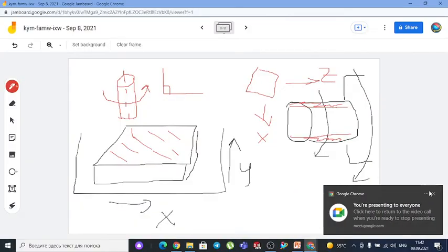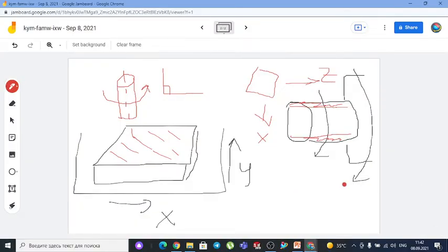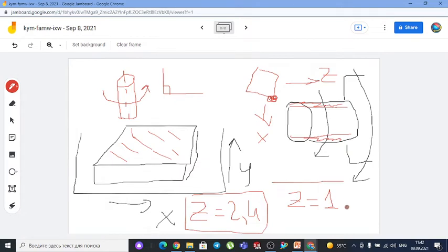Also, what I would like to highlight is that in the milling operation we have seen the z value. It was the number of teeth of our cutter tool. It ranged from 2, 4, 6, 8, 10 and so on for the milling operation. In the case of the turning operation, since we have a single point tool that just removes the material, that value is always equal to 1. Okay, it is important.